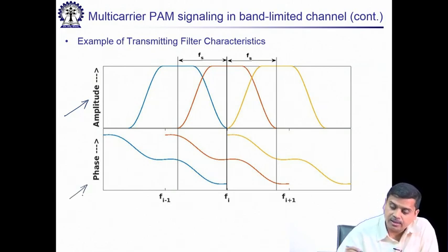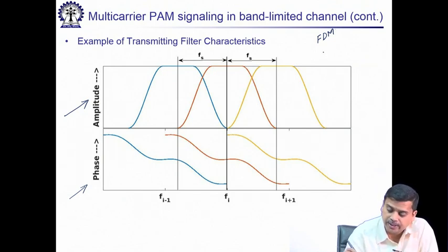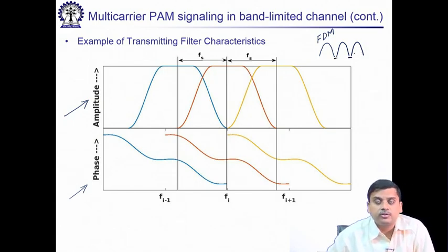What we see is that although we described initially it is a frequency division multiplexing mechanism, typically in a frequency division multiplexing mechanism, we had said quite some time back that one would have to put some kind of a guard interval between them, a guard band, which is a wastage, not used for anything other than reduction of inter channel or adjacent channel interference.